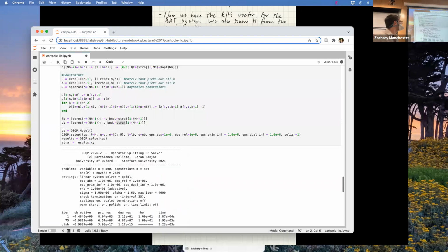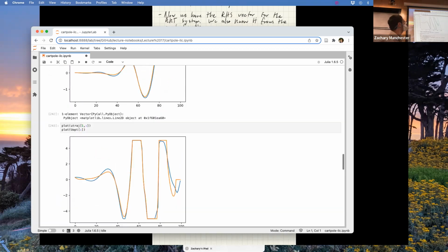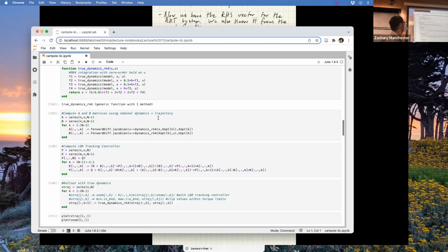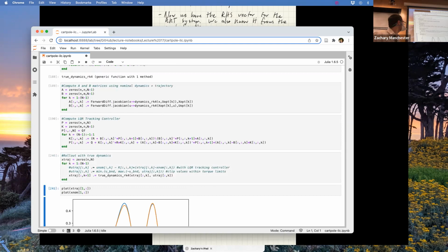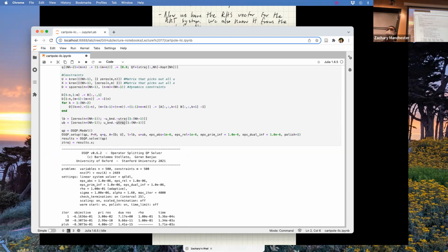There's still a little bit of tracking error, but it's swinging up and hitting the goal state, right? Which is what I mostly weighted in my cost function. I can keep doing this a handful more times, maybe I'll get marginally better, but now it's almost exactly nailing what you wanted, right? That was like 6, 7 rollouts on the real system, right? And then this kind of update on the U's. And this is running open loop also. There's no feedback on this, right? Okay.